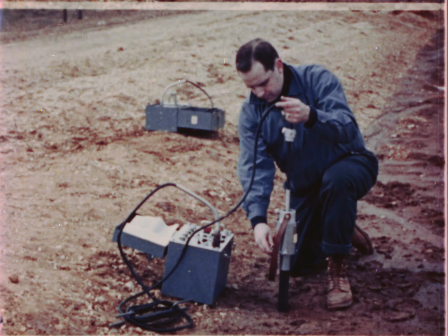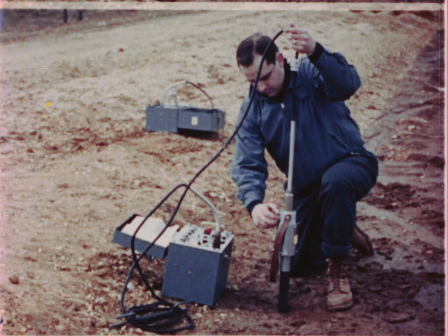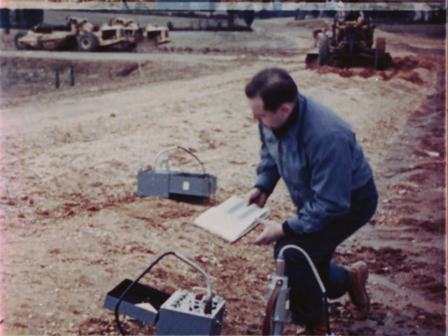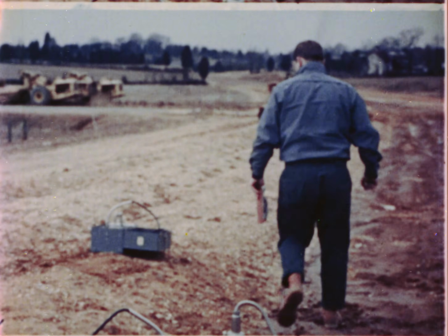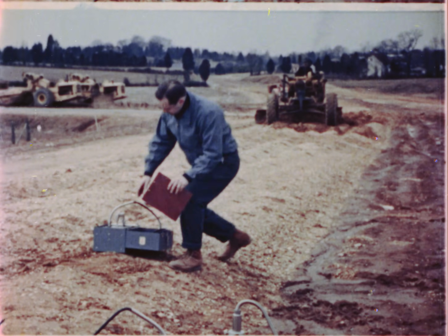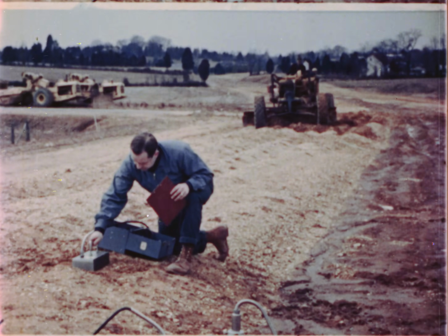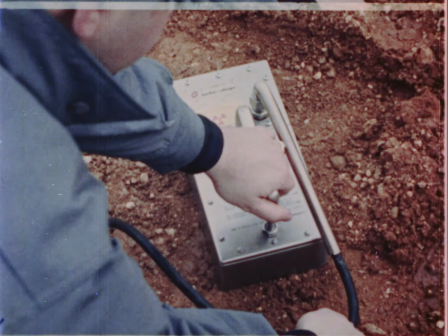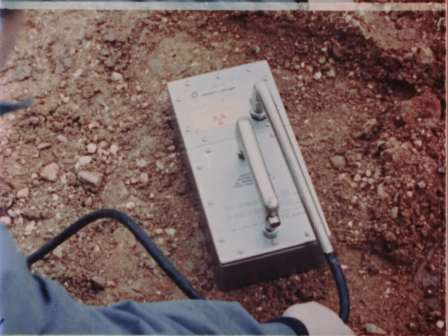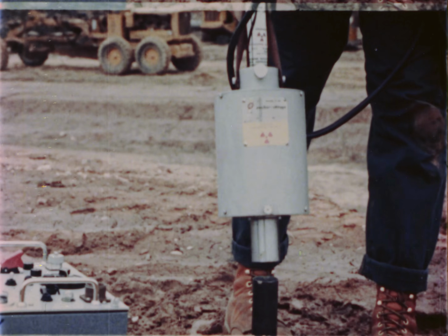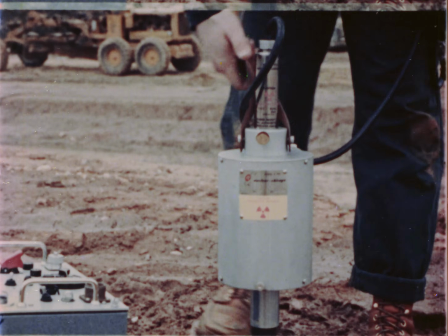Other thickness and density gauges employing the reflection or backscattering technique are used to probe surfaces and report on conditions below them, such as this instrument which can indicate the density of soil beneath a potential airport runway or highway roadbed. These gauges are so well designed and their source so well encapsulated that by following a few simple instructions, workmen can use the instrument safely.